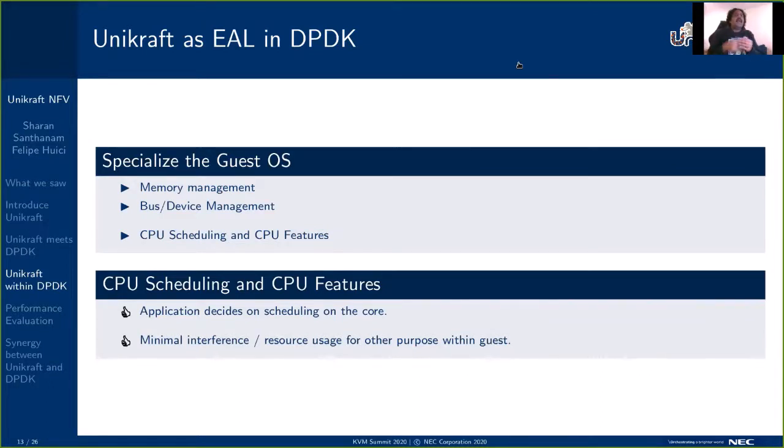And also, if necessary, we can completely do away with the scheduler and run the entire application in a polling mode, where everything is event driven or interrupt driven.